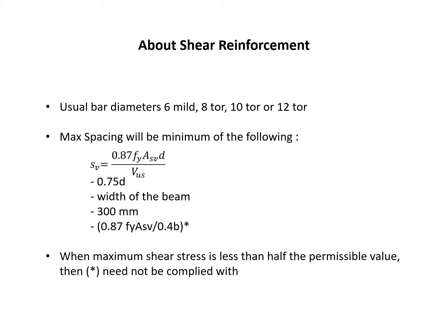So how do you design shear reinforcement? Very simple. You start with 6 mm bars and check all the spacing. If spacing is too close, then you go for 8 mm and give the spacing. We are going to do all types of problems in the next video, and all these things will be very clear. Thank you.